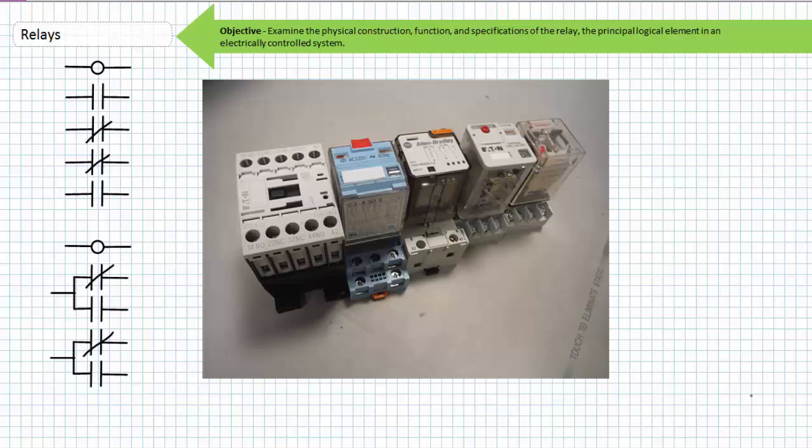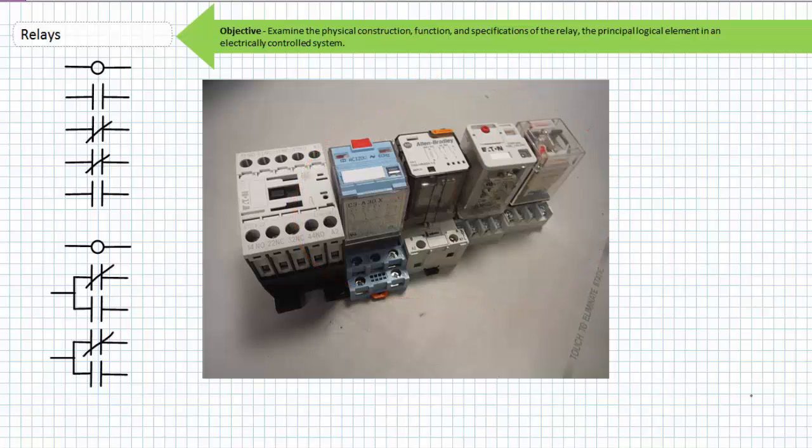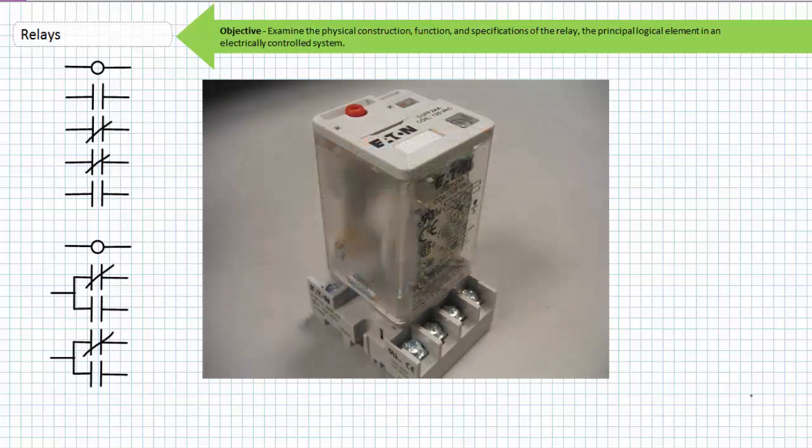Relays come in several forms, the two most common being the industrial or mini contactor relay, since it looks like a mini contactor, and the plug-in or IceCube relay, since it looks like an ice cube. IceCube relays come in many sizes, and it's a recommended practice to not put them in your drink. An IceCube relay has a matching keyed base into which the relay fits. The base is hardwired to the system, and the relay can be removed for inspection, maintenance, troubleshooting, or repair purposes.